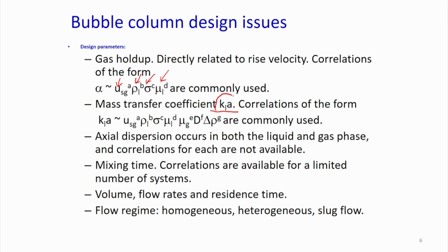These small particles of nano size bubbles or micro bubbles will behave like a bullet. They will not do any transfer with anything. So the K value will go down, and again increasing the surface area is not going to help you. So what we see, we want to maximize the KLA value. We don't want to only maximize A.